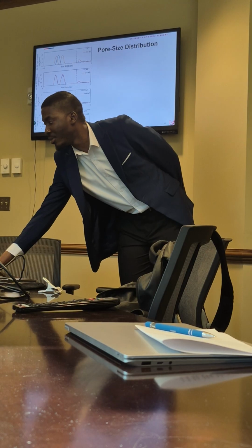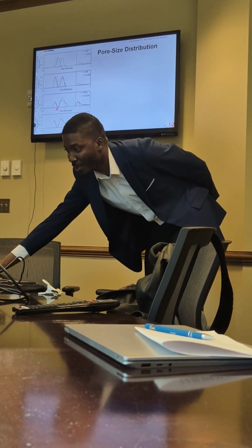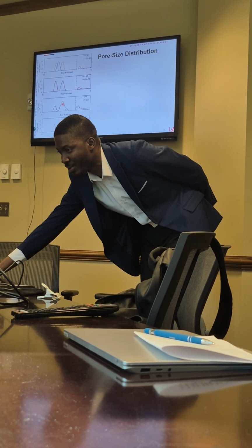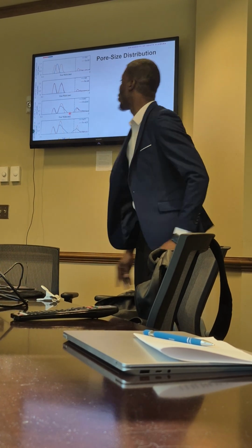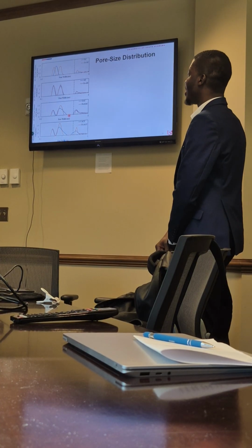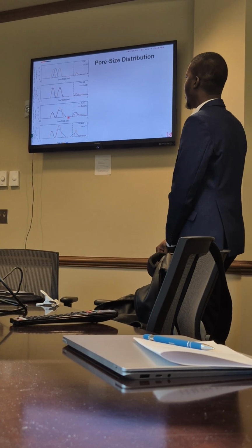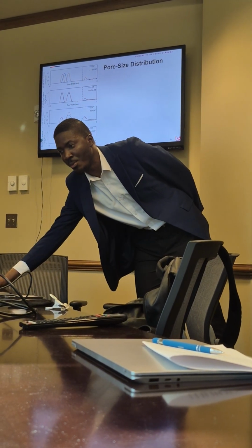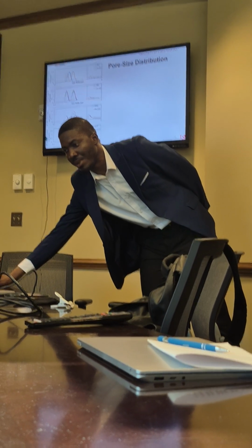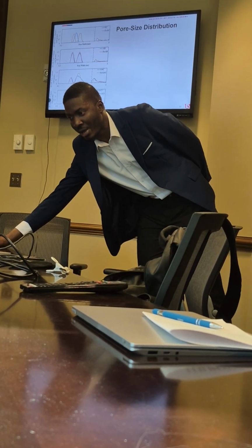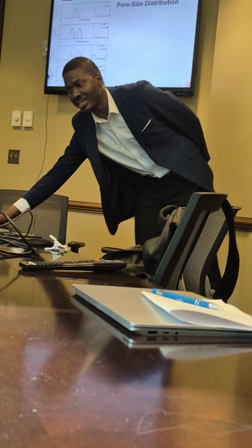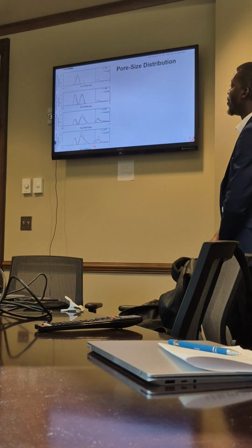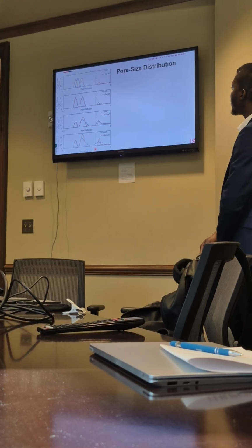For our ion GAC, we can see our pore width closing after ion modification because we had bigger widths. And this also confirms that indeed ion precipitation did block some of the pores of GAC. And we also saw something similar for ACF, whereby we had a broad pore width, which is characterized by the blue line. But for ion ACF, after ion modification, our pore width reduced. This also confirms that the pores were blocked after ion modification.